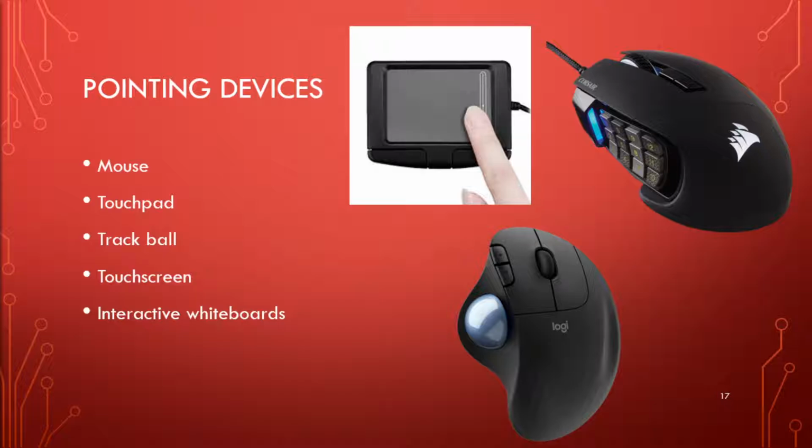There are two types. There's the older technology, which is resistive. This type is actually measuring the pressure on the screen. The problem with resistive is you touch down with your whole finger. It's not a precise point. So it's guessing where the highest pressure is and averaging it and saying, oh, you clicked here. And that might be to the right or left or up or down of where you actually wanted to click. So that's a problem. With resistive screens, I highly suggest either using your fingernail to get a very precise point, or a lead pencil that doesn't have the lead exposed. It's like a plastic thing. It's a nice way to touch it.